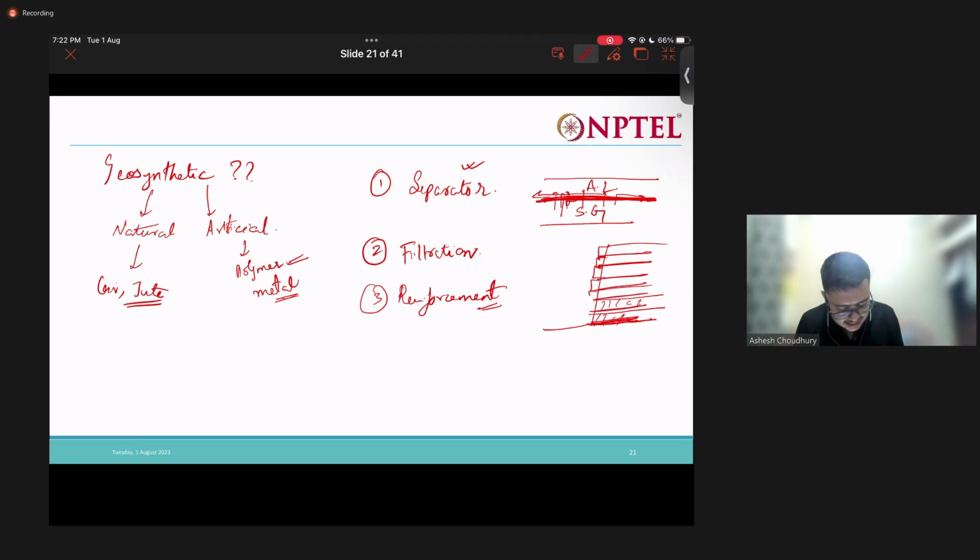The walls that we see here are just acting as a fascia. They don't have any other property. They just have to give a good look. So this fascia is used so that the wall looks good, right? This fascia is used to hold the geosynthetic in position, to tie the geosynthetic here, and also to give a good look. Then geosynthetics are also used for erosion control, as we discussed.